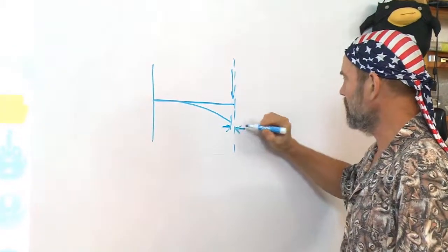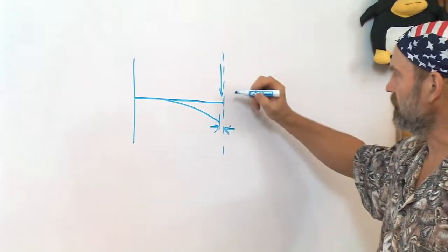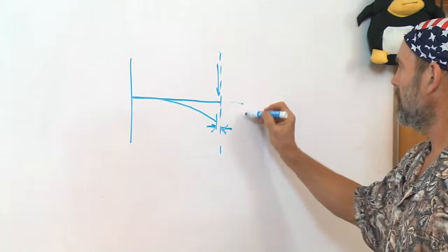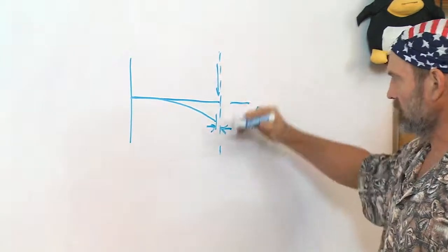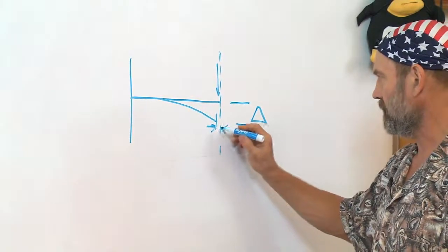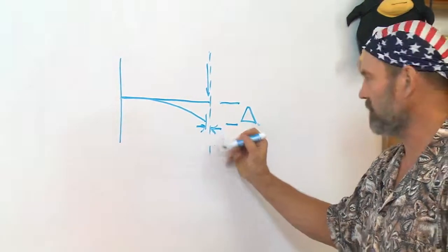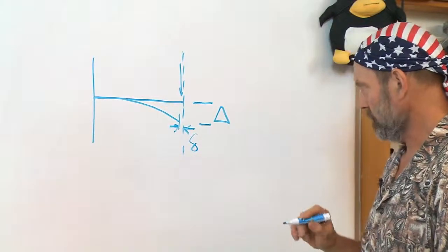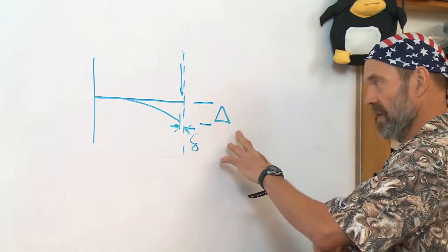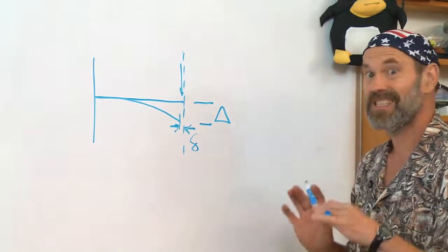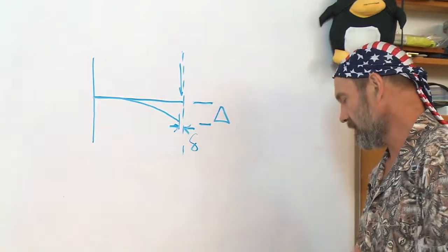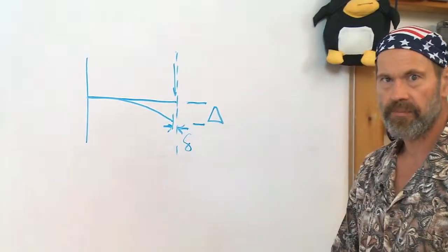You can read the formulas in the text and even their derivation. And that bending of the beam, if the large bending is delta, this little delta is the parasitic motion, because that's usually unwanted, is typically less than an order of magnitude smaller than the large deflection, but it's there. And for some types of structures, that can be unacceptable.